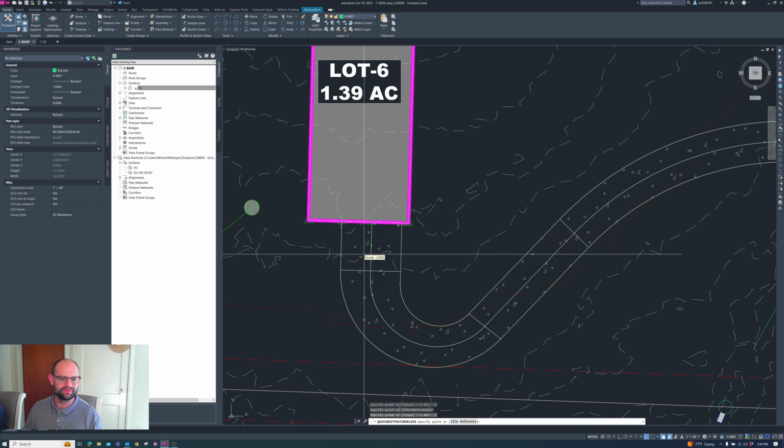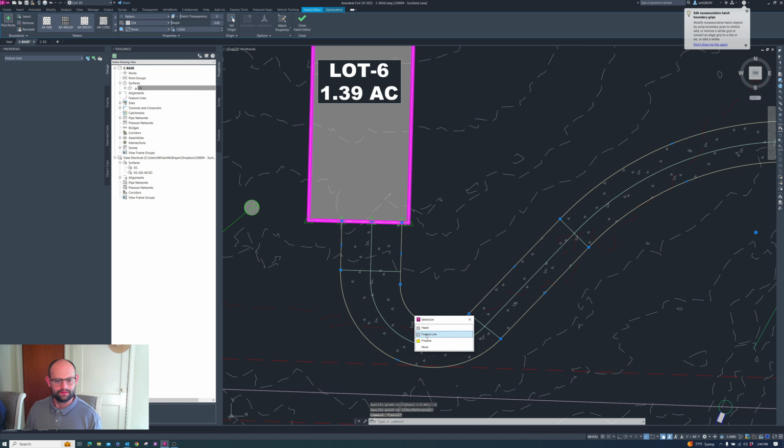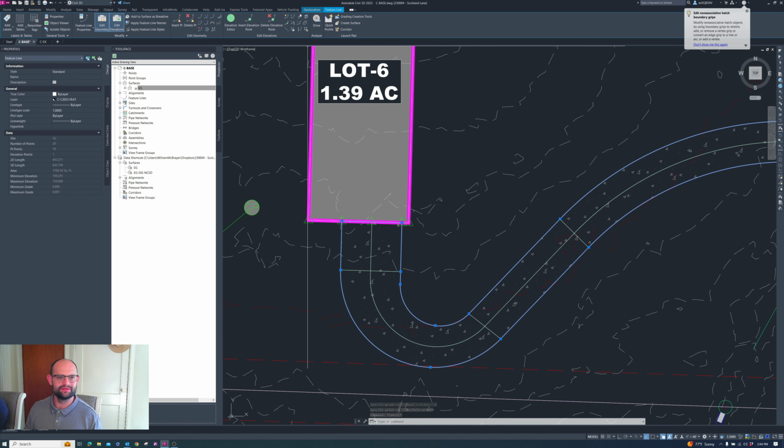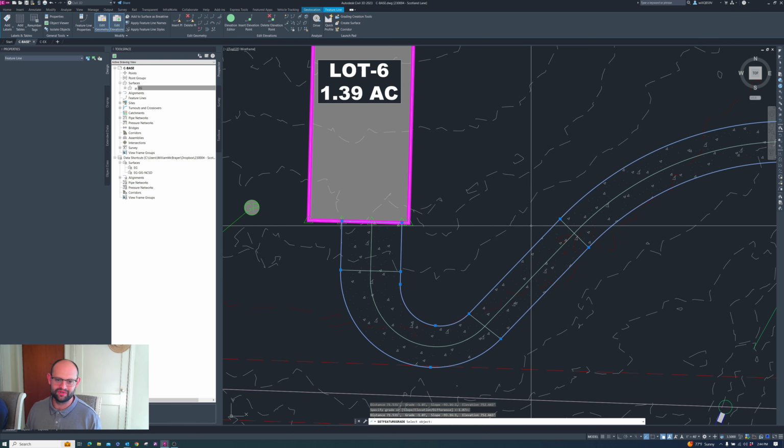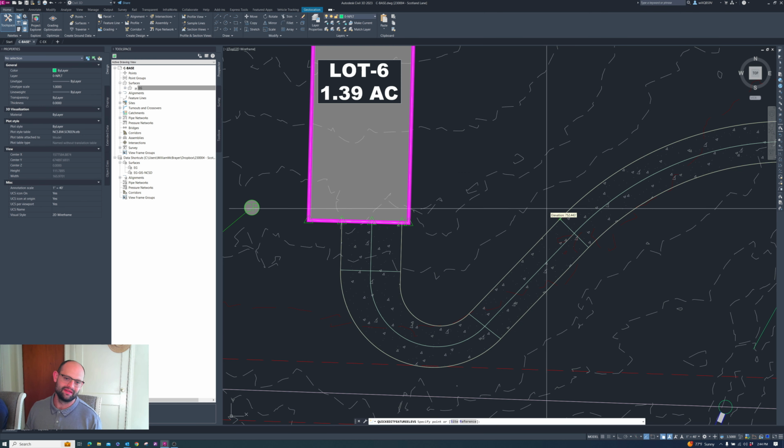Working down at 2% away from the garage. Let's reset this to a smooth slope between this point and that point, negative 1.07. That feels a little better to me.